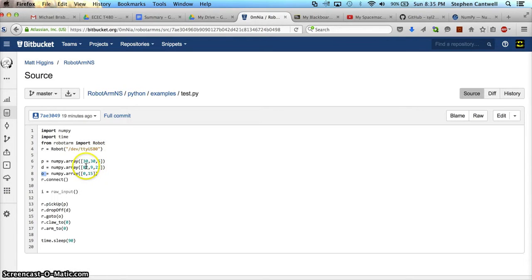And so the location of the item that we're about to pick up is at XY coordinate 30, 30, and the Z coordinate actually tells the robot how high up the arm will have to go to grab the centroid of the item. Next, we have the drop-off destination, and similarly, the drop-off is going to be at 87.9, and the height is going to be 22.